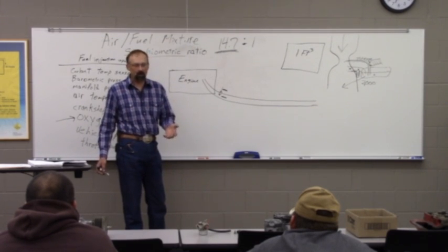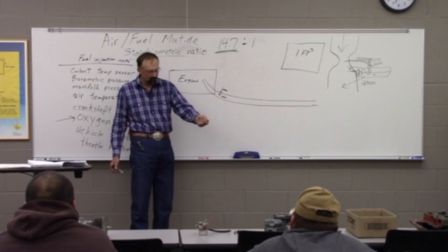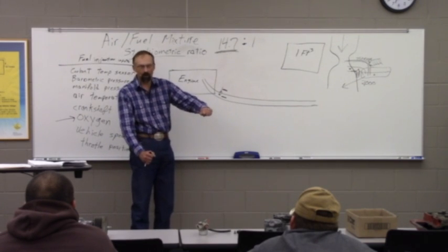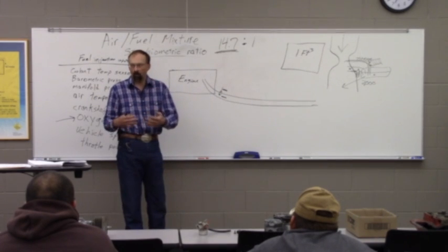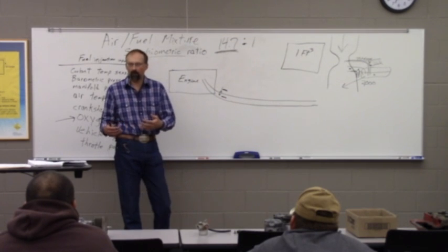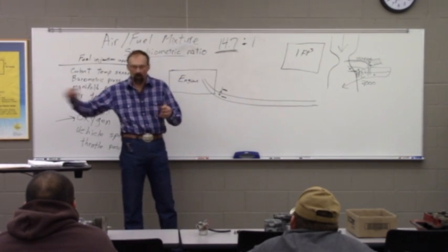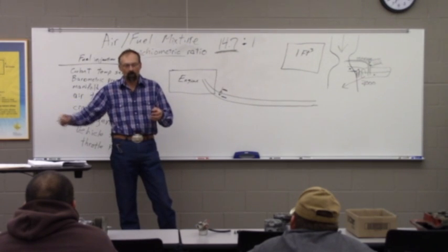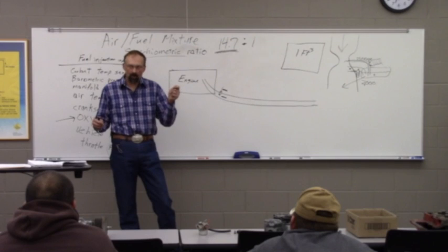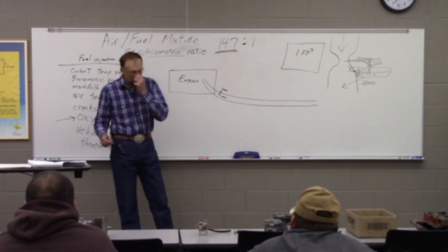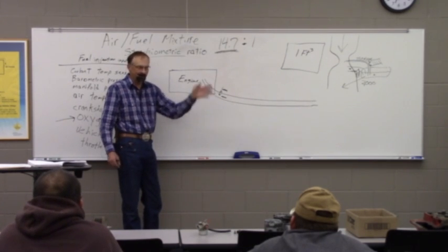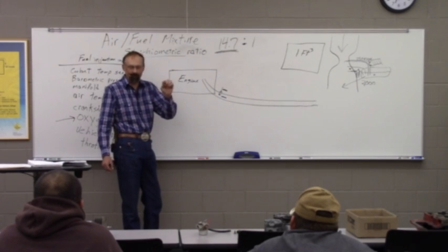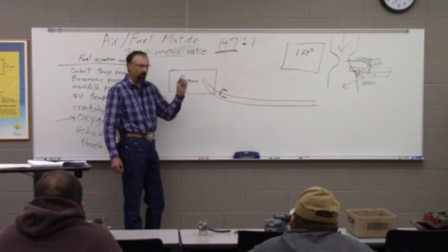When we're talking about amperage, it's more like the volume of the water. So if you're opening that faucet and you want a gallon of water versus you want a cup full of water, think about that more as the amperage. We're actually measuring the number of electrons flowing when we're talking about amperage. And when we're talking about voltage, we're talking about how hard it's being pushed. So this creates, I don't know, zilch point nothing for amperage. That's a relative term, but it's a very minuscule amount. But the amperage is what the computer's looking at.